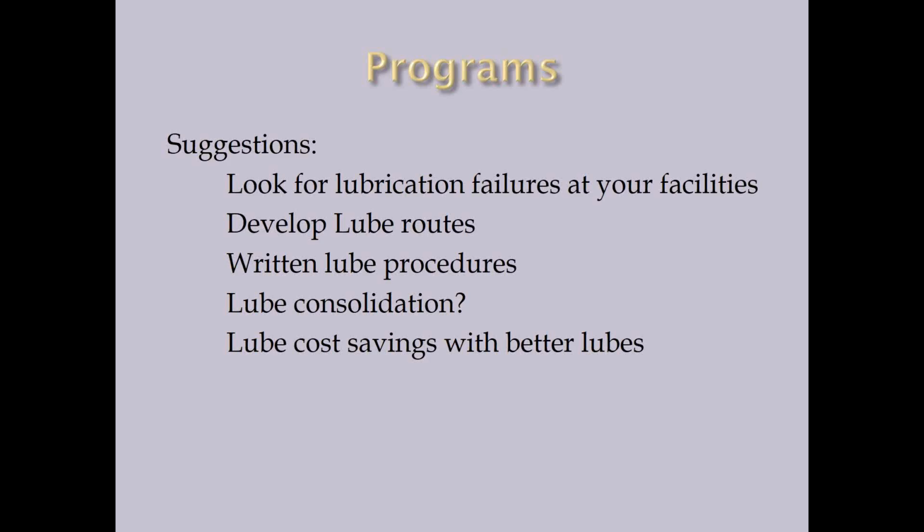So, look for some lubrication failure modes at your facility. Develop some lube routes. How are your lubes being checked? How's your equipment being checked? Written lube procedures: what lube goes in and how much? Can you consolidate your lubes, get them down to a smaller number of lubricants overall? This is something we can help you with. Even by internet, we can look at your lubes and give you some suggestions.